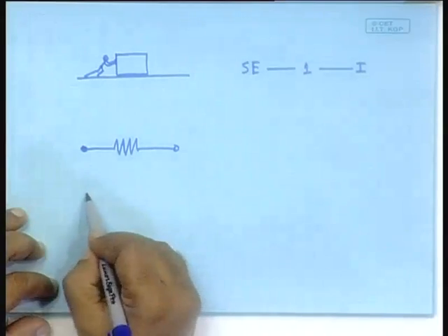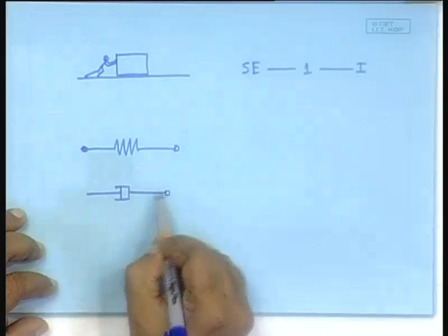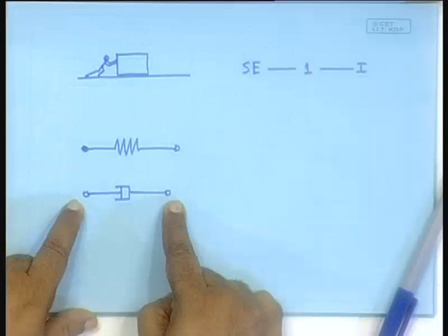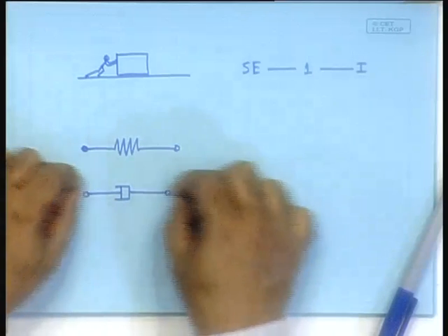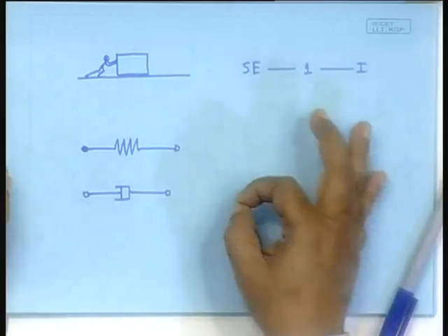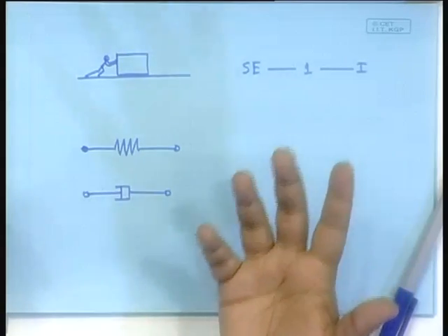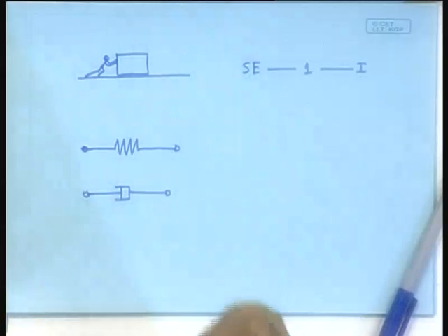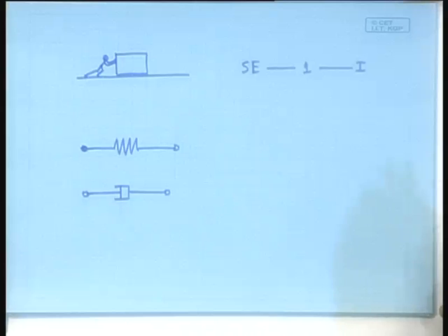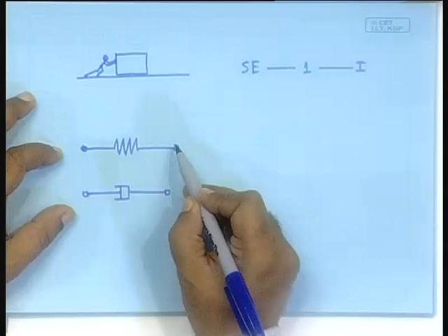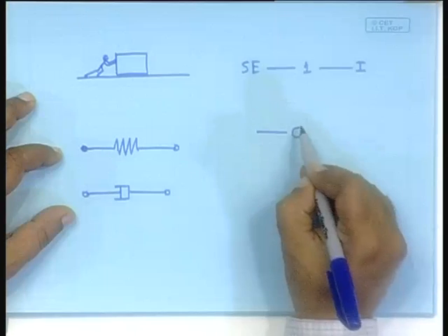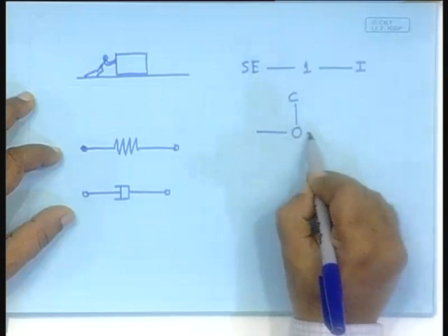Same is true for a resistive element. Just move them, the 2 ends must feel the same force, right. So, if these 2 sides feel the same force, then whatever is at the 2 sides, they share the same effort, which means they are connected by a 0 junction. So, in that case we will represent this as a bond, a 0 junction, a C element and another bond.